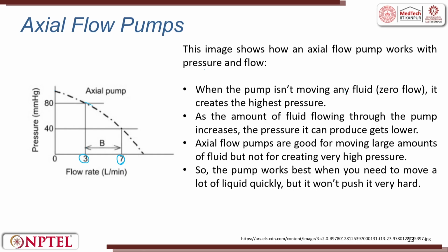When the pump isn't moving any fluid, zero flow, it creates the highest pressure. It is an idealistic case. As the amount of fluid flow through the pump increases, the pressure decreases. But in centrifugal, the fall was gradual. Here the fall is steep.